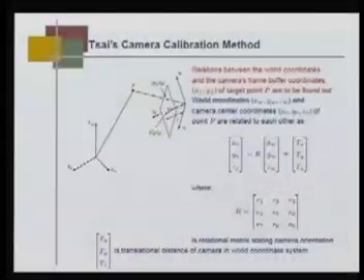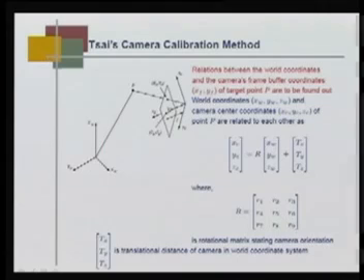But this in camera coordinate xc, yc, zc can be written very simply, that is by a rotational matrix R, which is R1, R2, R3, R4, R5, R6, R7, R8, R9, because this is a 3 link manipulator, plus the translational term Tx, Ty, Tz, where R is the rotational matrix stating camera orientation and Tx, Ty, Tz is translational distance of the camera in world coordinates.